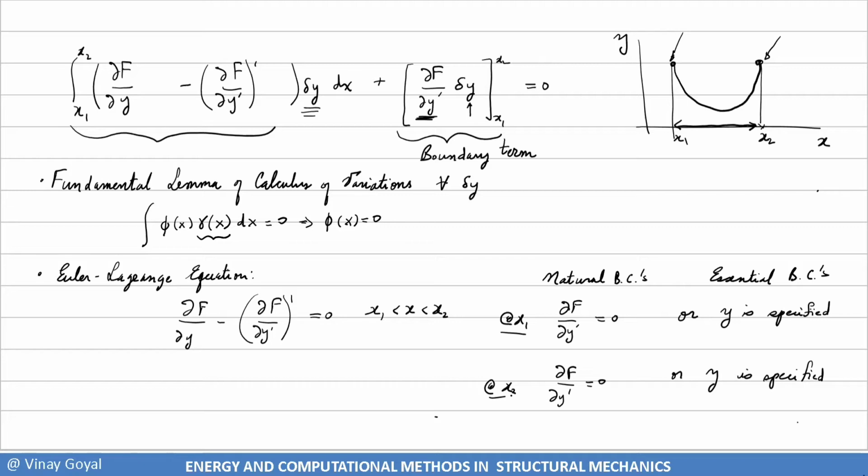So in our case, we did specify how the chain is going to hang. We told it exactly how it's going to hang. And so I know what y is, because I specified it. So as a consequence, in our case, you want to do a rectangle to specify that all the boundary conditions are essential. But if I had not specified the y here somehow, I left it free, then at x equals x2, this must be true, and not that one. And I'll cover an example coming up on that.